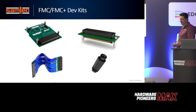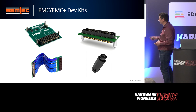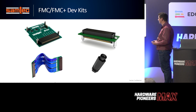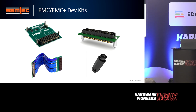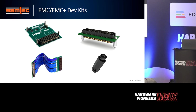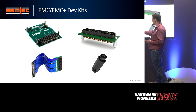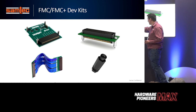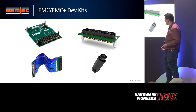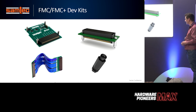We work a lot with Vita and FPGA manufacturers, so sometimes they ask us for different features. So we have some tools that are helpful for designers. So if you have a very expensive FPGA kit, 10 grand maybe, and then an FMC card that is 2 grand, you don't want to really jeopardize it because you don't make a proper mate into the connector, because they are high retention. There's a lot of pins in there, high retention. So we started to work on FMC extenders, for example, so you can have your FMC cable directly into the card and then just plug the cable into the mezzanine card.